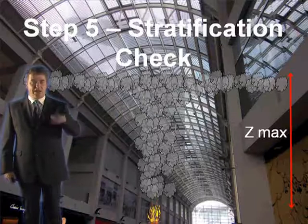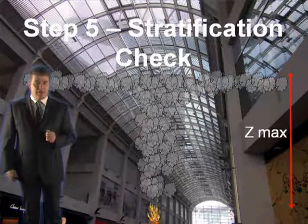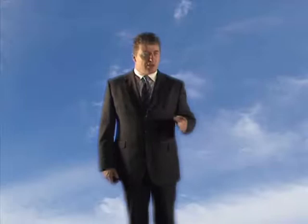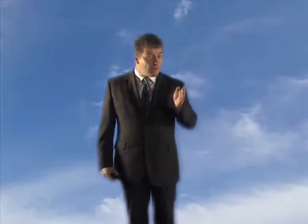You're extracting it as it leaves the shop. There's no problem there. So let's go straight on to ventilation requirements, which is step 6. Now, we know how much smoke is to be extracted, and this is 31.2 kilograms a second. However, fans are rated in metres cubed a second, so we need now to convert this to a volumetric flow rate, taking into account the fact that the smoke will be very hot and will have expanded quite considerably.